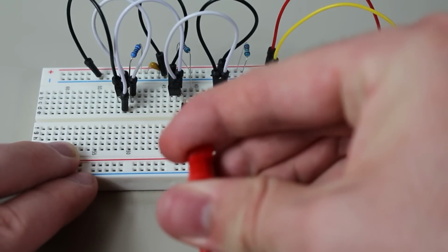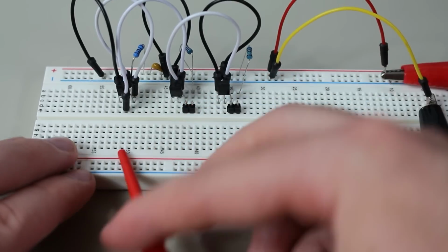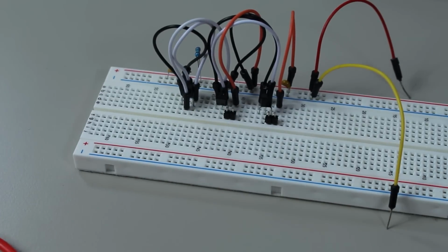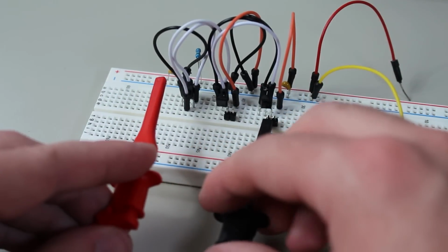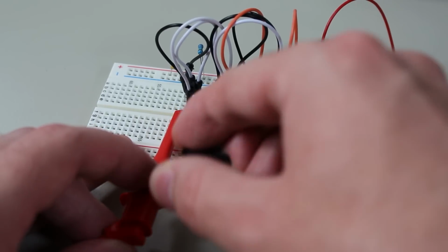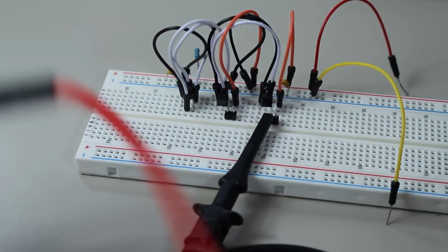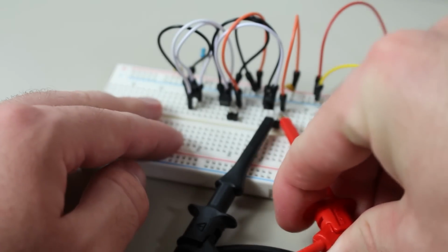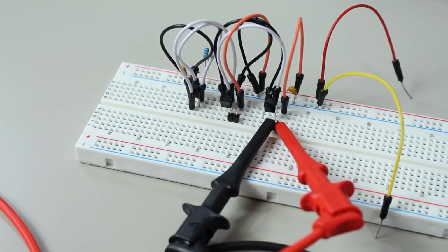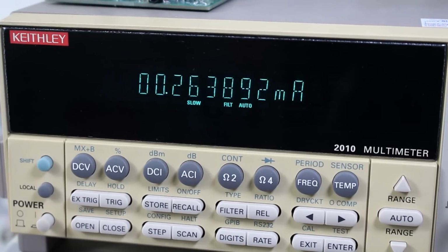At just 22 ohms, they were 11.25 milliamps and 9.71 milliamps respectively. At 220 ohms, they were 1.93 milliamps and 2.1 milliamps. And at 2.2 k ohms, they were 641 microamps and 293 microamps. This is definitely interesting because it demonstrates how increasing source degeneration greatly improves matching, but it comes at the cost of greatly reducing your gain.